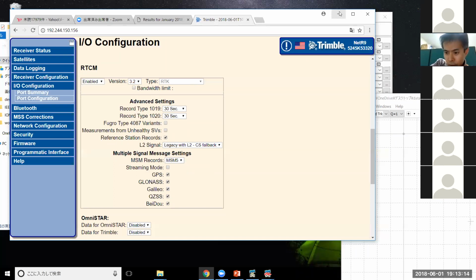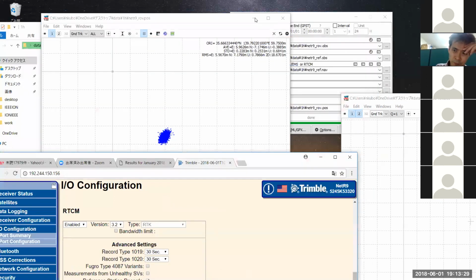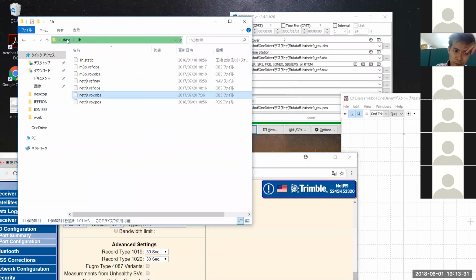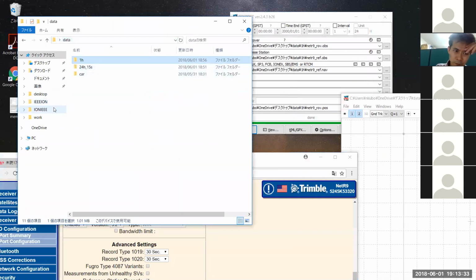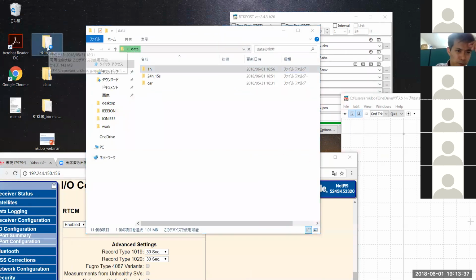If we have, say, a u-blox base station, we need an Ntrip server, and then we can broadcast using the Ntrip server. We call it the caster, and in the field we have the Ntrip client. From the field, it will access the Ntrip server to get the base station data, for multiple users.